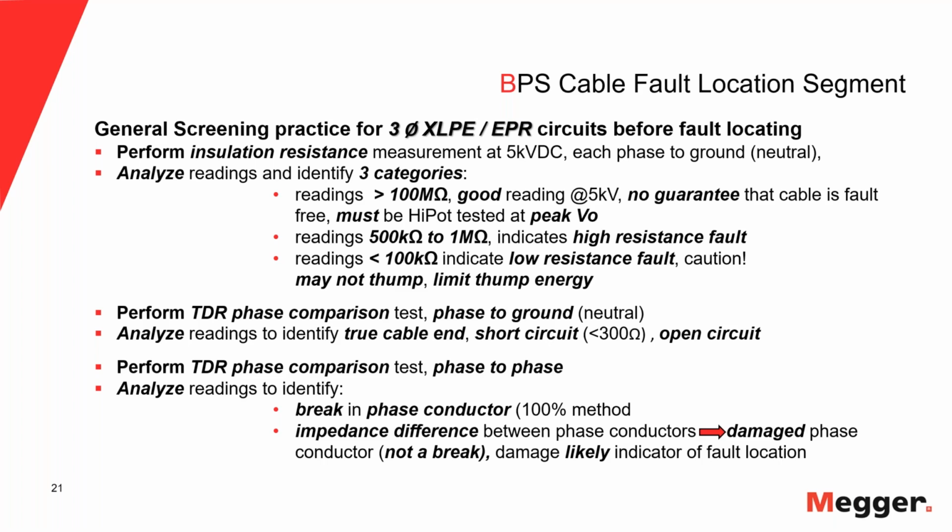And anytime you see some wiggle on the screen, that means it's either up or down. That means a higher impedance or lower impedance than what the characteristic cable impedance is. Many cables in these distribution cables are 50 ohm cables, and so if you suddenly had a spot where you only have 10 ohms, you would see a downward blip. If you have suddenly a spot where you have maybe 150 ohms, you have an upward reflection. You still see the end of the cable, however.